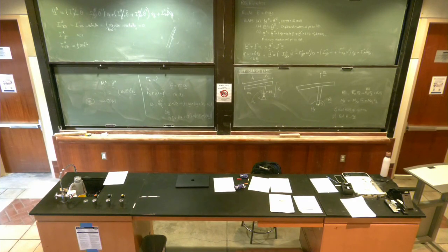I'm considering the system to be the horizontal and the vertical bar. That's what I asked you. Okay, that's your free body diagram. No, you see, you're considering the system to be the combined horizontal and vertical shaft. So any internal forces here don't come up in your free body diagram because they're internal.